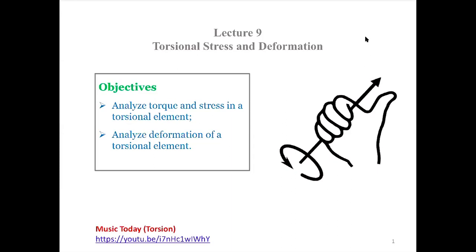Here the internal force will not be the axial forces anymore. So it's torque, right? When you apply a torque to a shaft, we normally call the element that is subjected to torsion a shaft. When we apply the torque, a shear stress will be generated, only shear. If we consider this a bar, I will apply torque to twist it instead of pushing to shorten it or stretching to elongate it. This will be a different story.